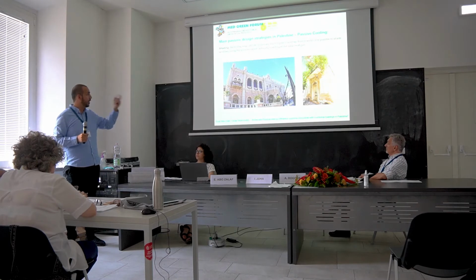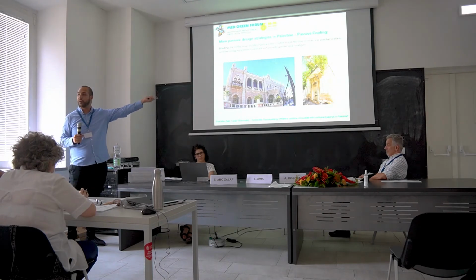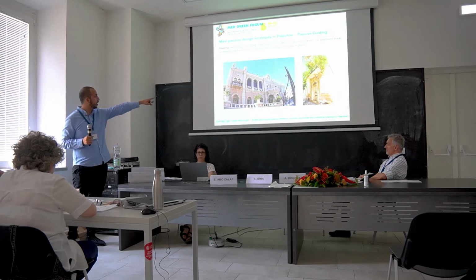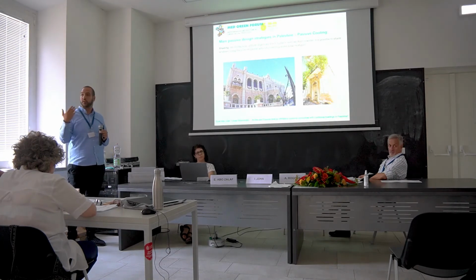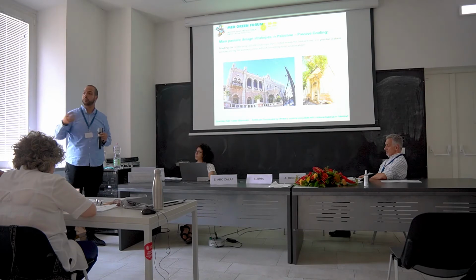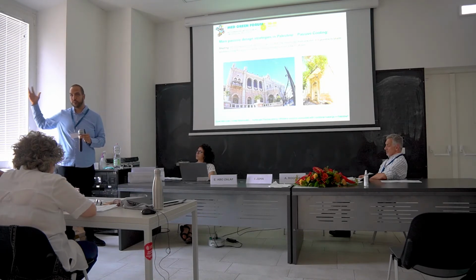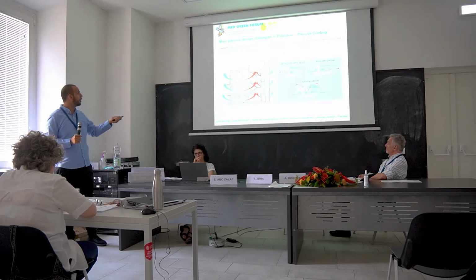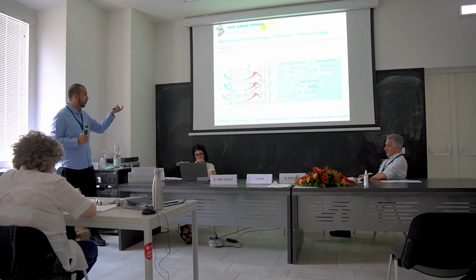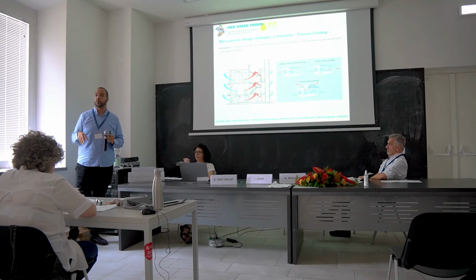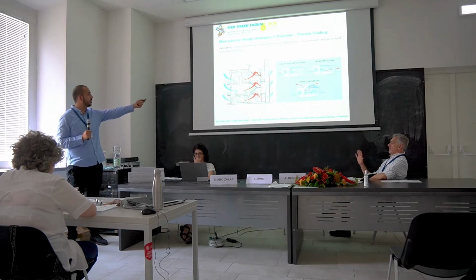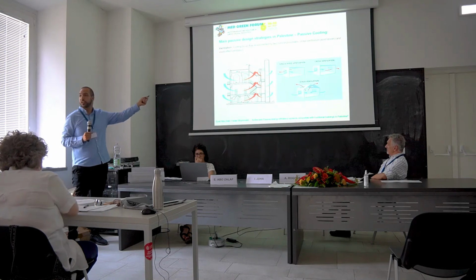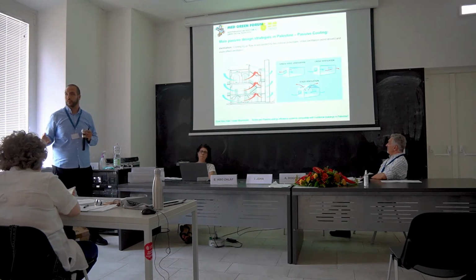Also here, you can see the balconies with the planting they used at the entrances. You can see how the windows are set back to the inside, so they give shading from the elevation itself. Of course, the ventilation I wanted to speak about before: you can see here the cross ventilation, which relates to the buffer zone.